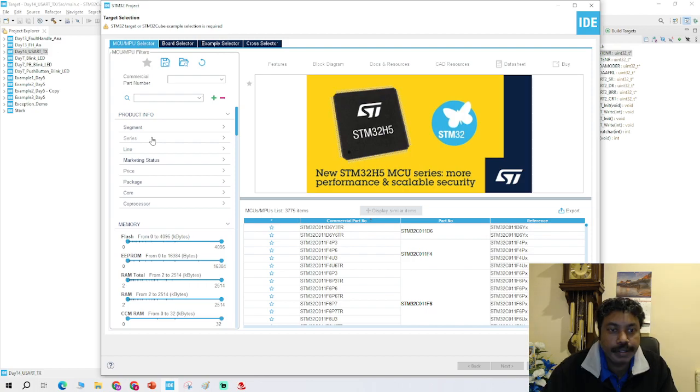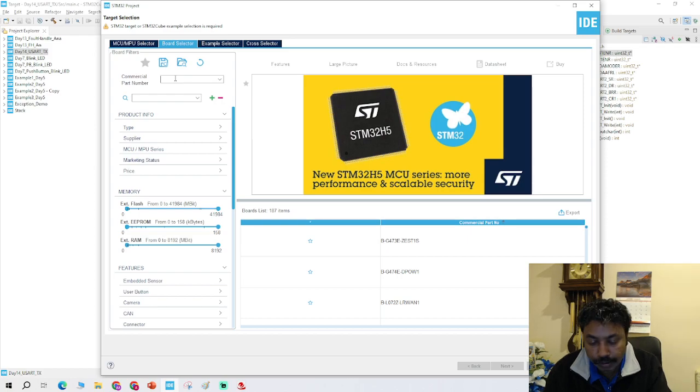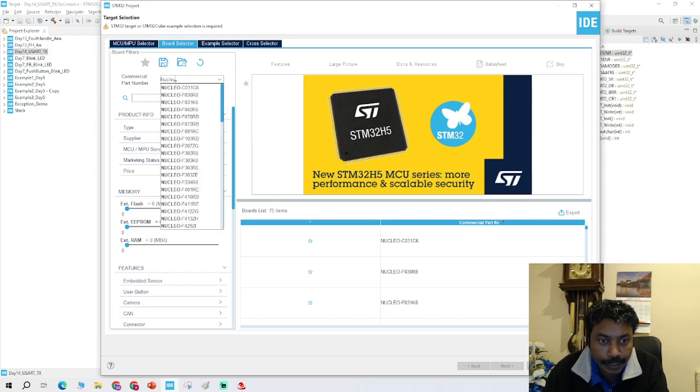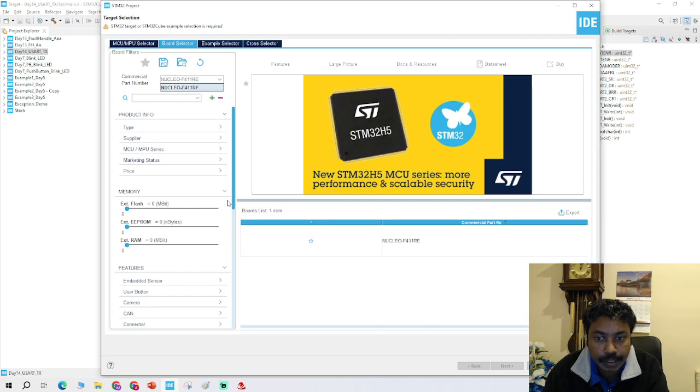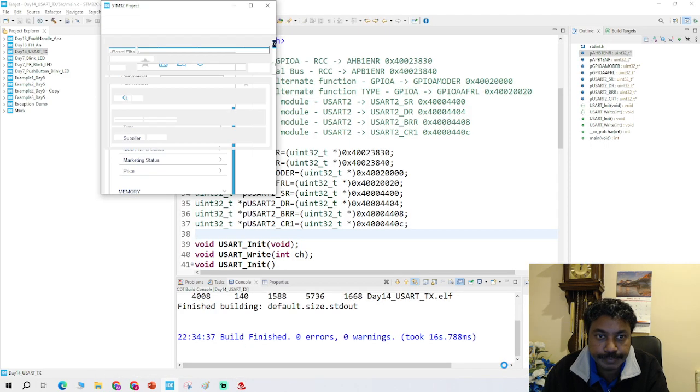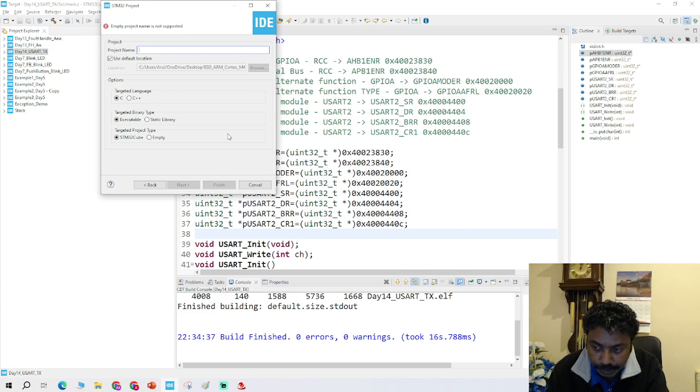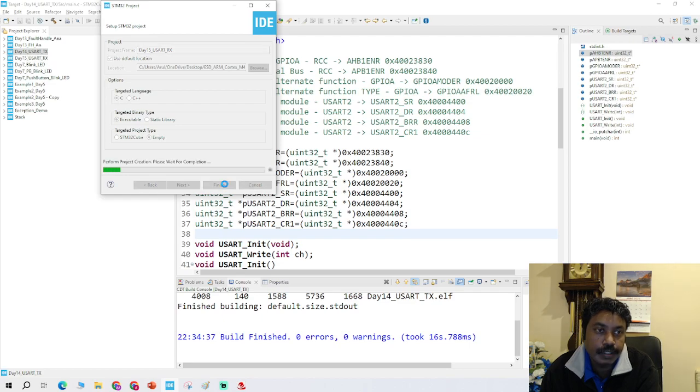Okay. Here we are. So we got to select the board. As you know by now, we are using Nucleo F411RE. So select that board. Click next. Then give a project name. Today is day 15, so I'll replicate that. Day 15. You're going to learn USART receive today, and then select STM32Cube for targeted project type. Finish, and this will create the files as you can see.